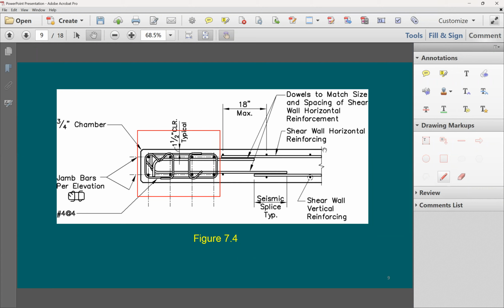What's the definition of rho n? Rho n is the horizontal steel ratio. Whatever horizontal steel ratio you have, if you multiply it by the shear area, you're going to be getting AS. Because rho n, this steel ratio, equals AS divided by ACV. So when you say ACV multiplied by rho n, it is going to be equal to the steel cross-sectional area.